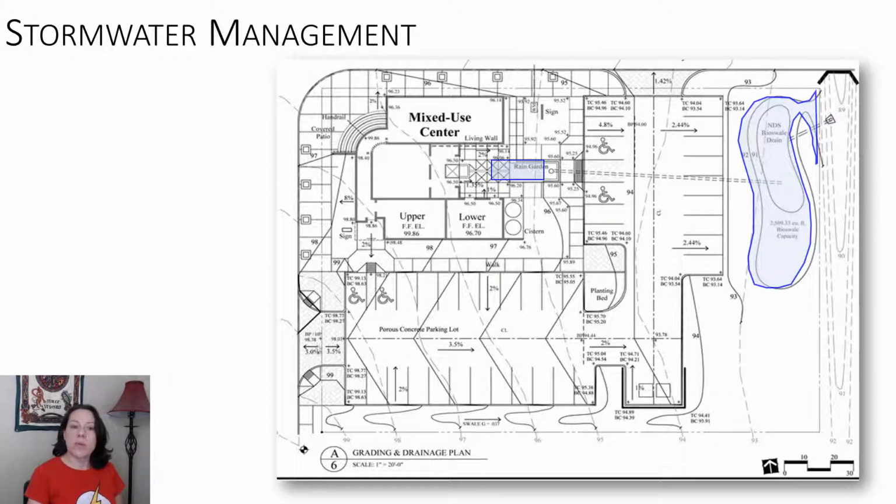Now, you can only allow off your property a certain amount, or you can only let off to the right of way. So notice there's a ridge right here. There's a high point. So they're sending water off into the roadway over here and off into the roadway over here in their driveway, but they can only send what is from the property line, and that's this line right here that you're seeing. Again, you can see the tie-in of the existing grades.